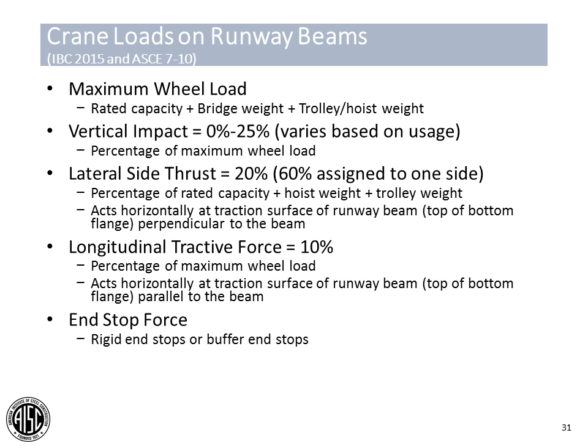We actually recently worked on a design where we had to consider differential settlement in the footings as well, because we had different soil conditions along the length of our beam or the length of our building. So you need to look at the entire system and the general deflection and serviceability criteria for building design, for the specific components that are supporting the crane system. This goes both for underhung and top running crane systems.